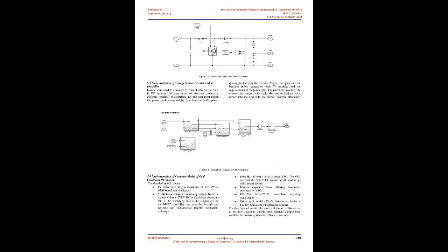3.1.3 Parasitic capacitance method. This method is an improved version of the incremental conductance method, with the improvement being that the effect of the PV cell's parasitic junction capacitance is included in the voltage calculation.